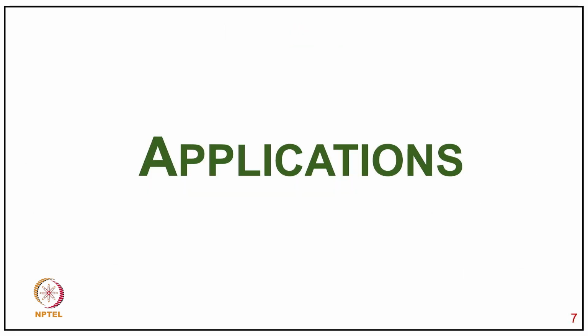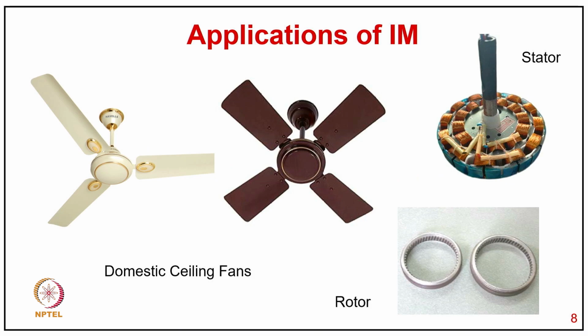Now, coming to applications of the single phase motor, one of the major applications is in India, where around 3 crore induction motors, out of 3.5 crore, are manufactured every year for use in ceiling fans, especially the domestic ceiling fan, as you can see in the photograph, and how the internal winding structure is. Typically the stator is inside and the rotor is a cage rotor, which is normally put outside. So this is a little different kind of construction, made for the specific application of your ceiling fan.